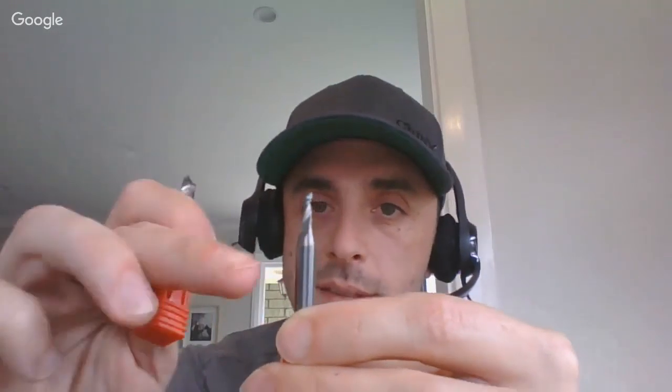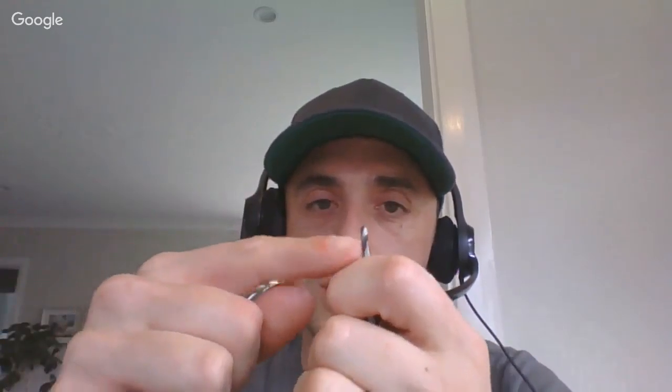Now, Leslie's come back and he's asked something. He said, what's the difference between, say, a 3mm tool versus a 6mm tool when you're talking about feeds and speeds? Okay, it's a great question. The 3mm tool is obviously not as rigid. We try to make our tools as rigid as we can by keeping the shank at full diameter, as close to the cutter as we can. So we've got this taper in here to improve stability rather than just necking straight down to 3mm. So the rigidity thing is an issue. You can't push it as hard if it's not as large a diameter.